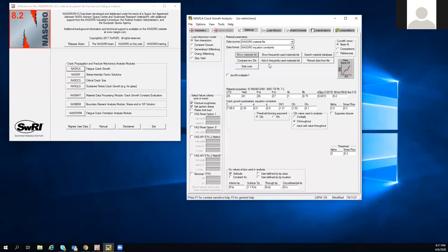Now, it's important to know that in practice, NASGRO is still just a calculator that needs an intelligent engineer to govern what it's doing. There are some cases, depending on the material and the geometry that you're using, where the net section stress may exceed your flow stress, and you, the engineer, might decide that that's acceptable. What that means is that your part is yielding.